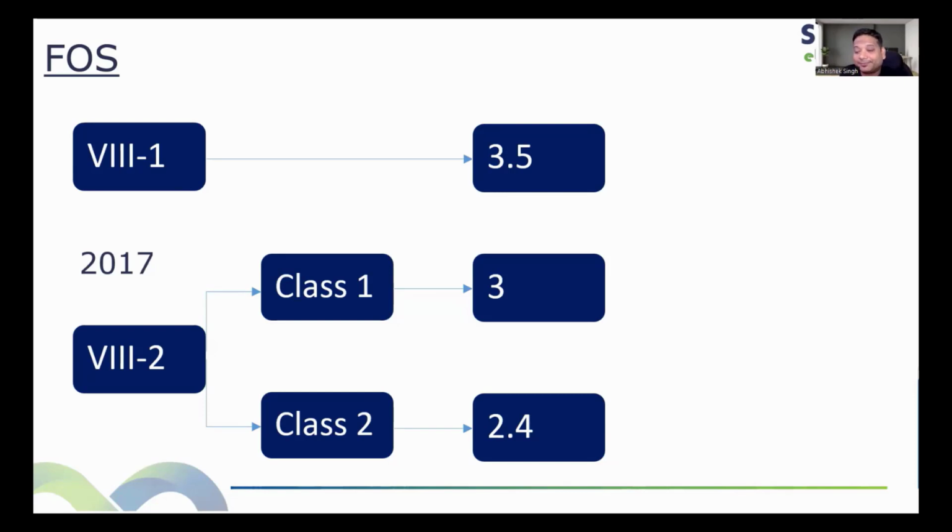Is it making sense, guys? So Class 1, no need to do FEA if fatigue is not there and all the rules are available. For Class 2 also the same. Now, I'll ask again one question related to Class 1. If the rules are already there for Class 1, for Class 1 we are following Part 4, there is a formula for thickness calculation. Can I use Part 5 and overrule this design?